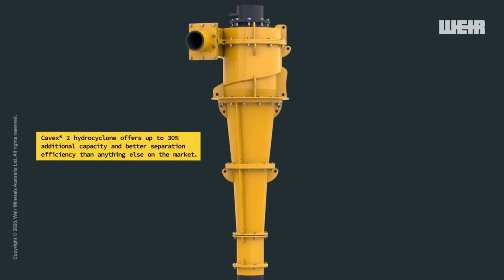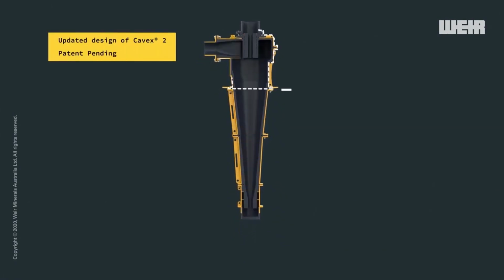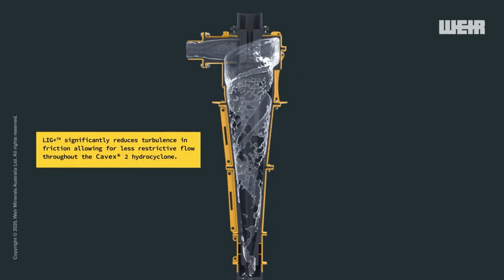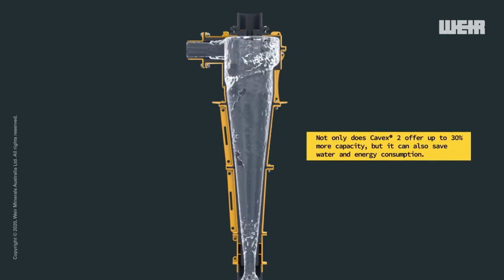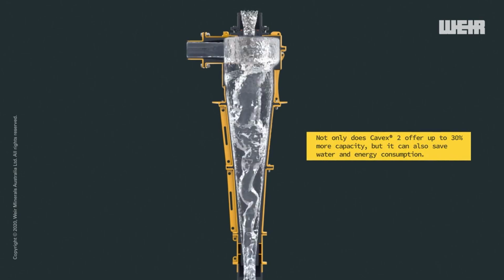And it's remarkable. They have a geometry completely different from what was expected, because we expect one cylindrical chamber followed by one conic chamber. They can have different chambers, and they have this spigot where you put the apex at different sizes and different places, and this actually does the trick. So you can see, only with water, a good simulation just for you to understand how a hydrocyclone starts, and then you can see the vortex being formed.